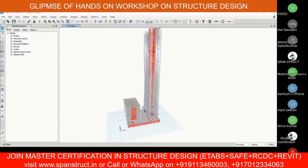So if you're doing 100 projects, in that 80 of the projects you will be doing through this step, which is very common, importing .dxf floor plan. It's a very easy step of creating the mathematical model. So now you might be getting a very clear picture of which step we have to learn very well to create the mathematical model in ETABS. And .dxf floor plan is a very good, reliable and very easy step for creating the mathematical model in ETABS.